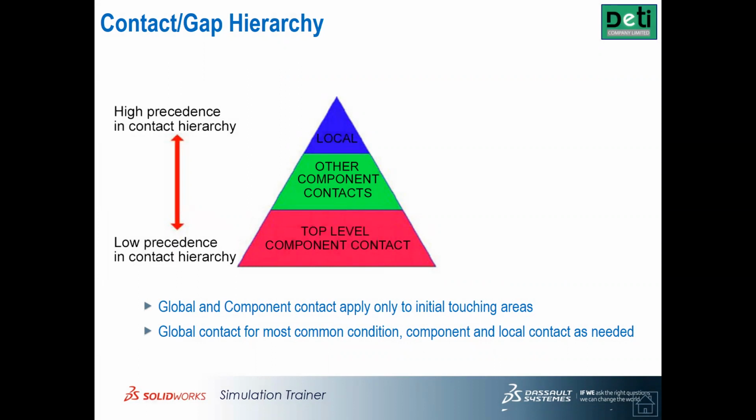We just guess the two arms will go into contact. And for the contact, in the connections options in module 3, when we say component contact, that means the top level down there, the red color, is like a global contact that we have to set for the assembly. And then we have another contact: in our assembly we have 3 interferences that we already set for all, which is global.